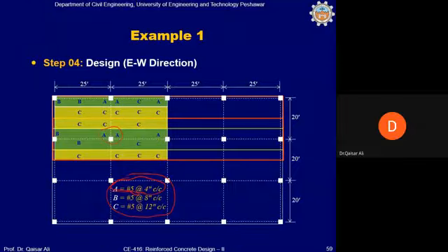However, we have used the spacing of 4 in center to center here at the column strip negative interior bending moments at location A. At location B, the value is number 5 at the rate of 8 in center to center, double of this, because the bending moment was almost double of this.